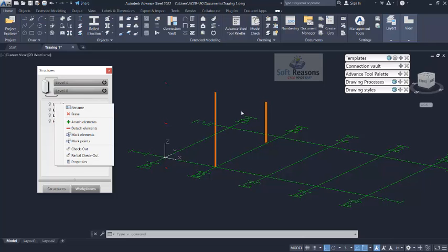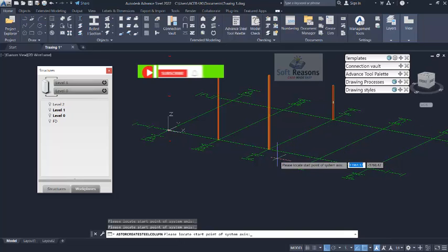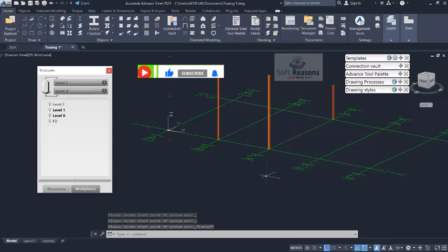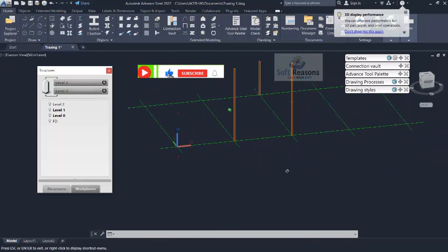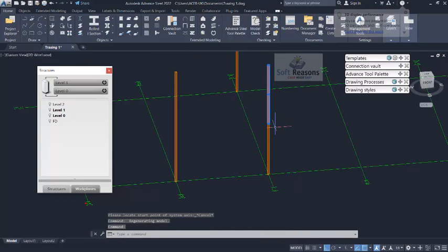All right, but I want us to look at how we can view the plan of each of these levels successfully. So now we have a column on level 2. We have a column also on level 1. Let's place another column between the level 0 constraint and the level 1 constraint. Pick that right away and select this point and this point right here. After which click on the close options. You can hold the shift key and the wheel of the mouse, press it down and move your hand. So it seems you're having two stanchions here. We can easily get rid of that.